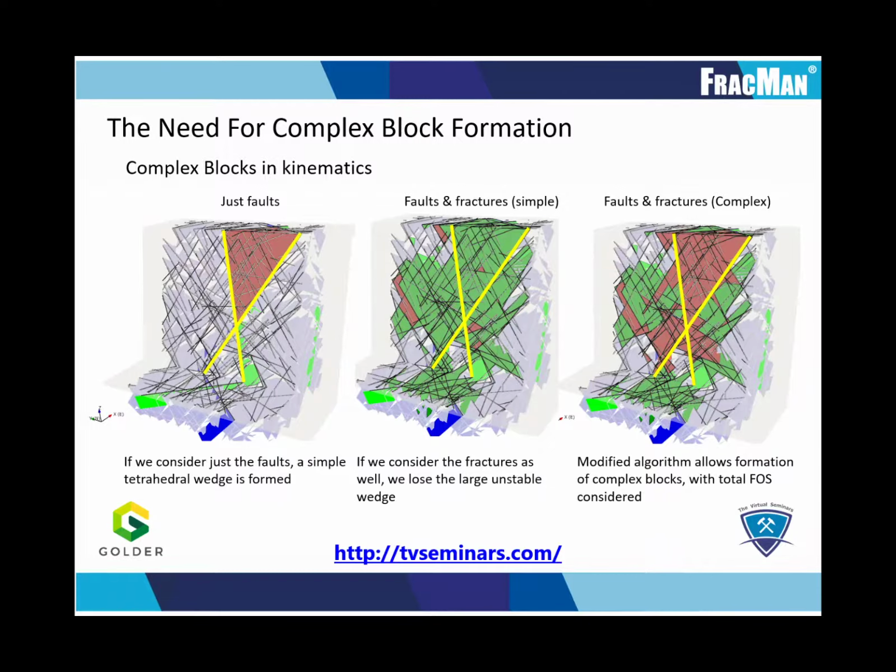In the middle case, these 2 faults are embedded within a broader joint fabric, and because traditionally the kinematics are evaluated from the blocks attached to the free face, the stability of the joints defined blocks are stable, rendering the fault-defined wedge also stable as it sits behind.